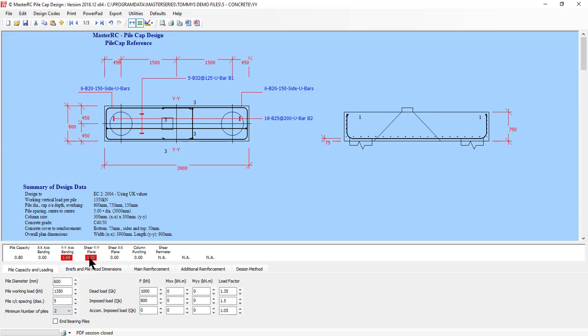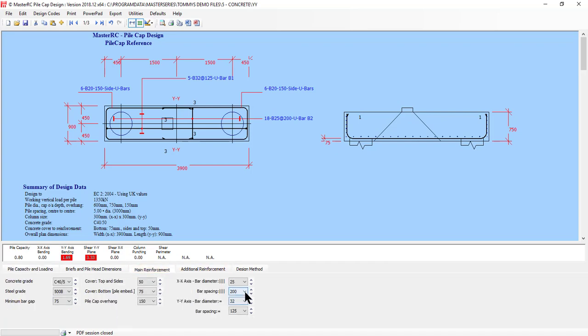If this was required, what you would be looking at doing is putting in an awful lot more reinforcement and seeing if that improves it. It's not really the bending that's the problem, it is the shear. As you can see, if we went up to 40mm bars, we have no bending problem, but we still have this shear problem. We just don't have the shear plane for doing that.